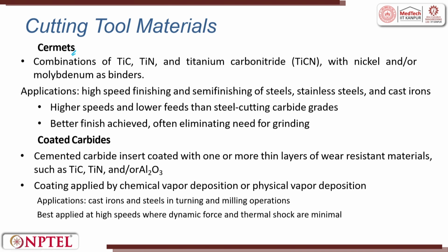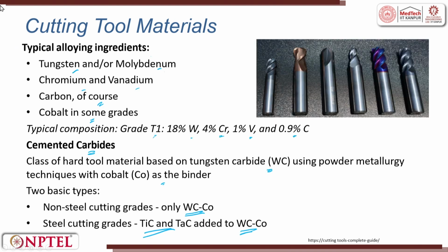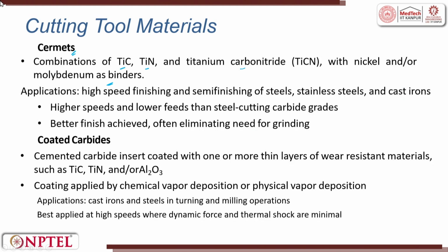Cermet tools are also there. It is a combination of TiC, TiN, TiCN with nickel or molybdenum as a binder. Again, here it is an insert which is used. So, friends, solid tools will be HSS, and all the other tools are inserts. Higher speed and lower feed can be used with the steel cutting grade, and a better finish can be achieved.